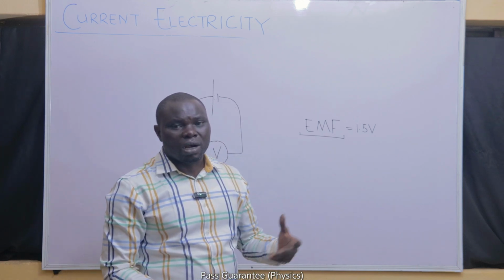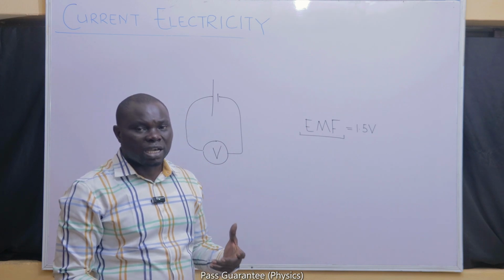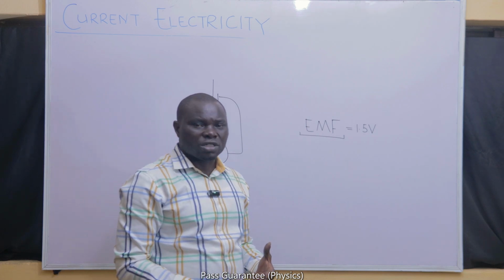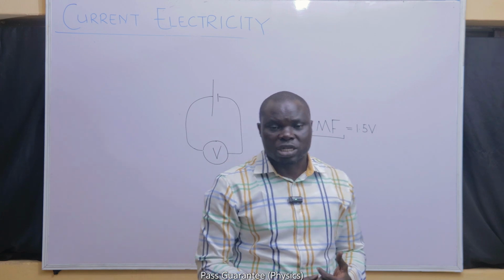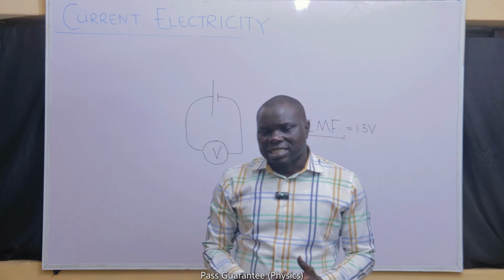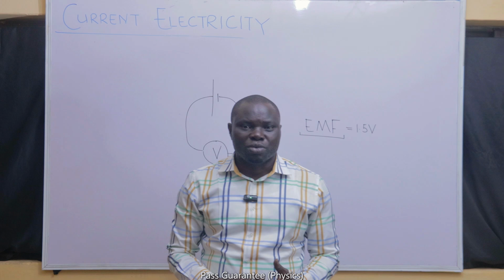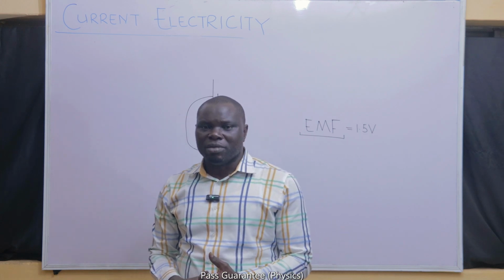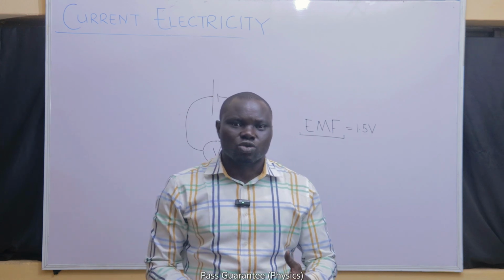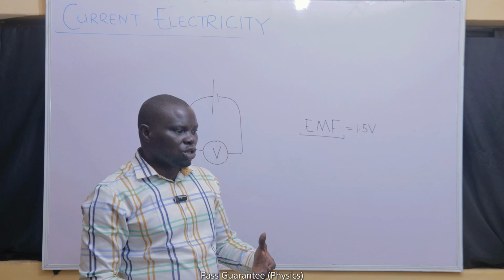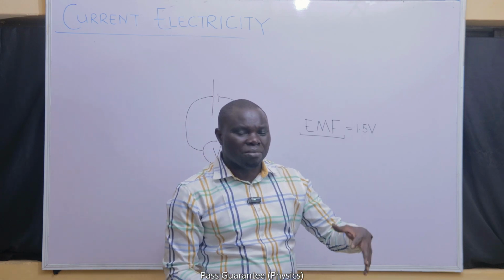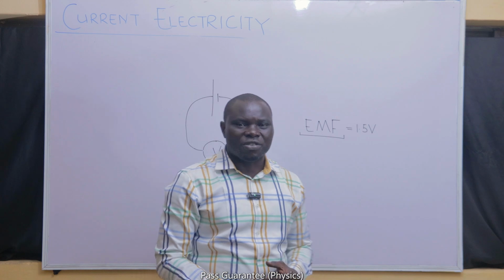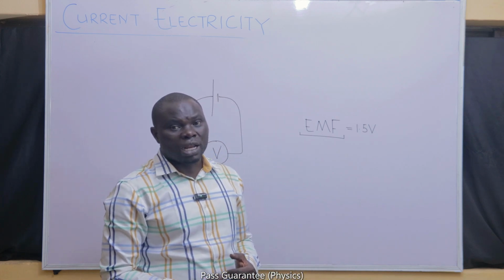I had earlier talked about the electric cell and the defects of a cell, that cells experience what is called polarization and local action. Yes, this effect can be minimized, but it can never be completely eliminated. As the cell starts to work, polarization will start to take effect. You have your depolarizers that will minimize but not eliminate the effect of polarization.